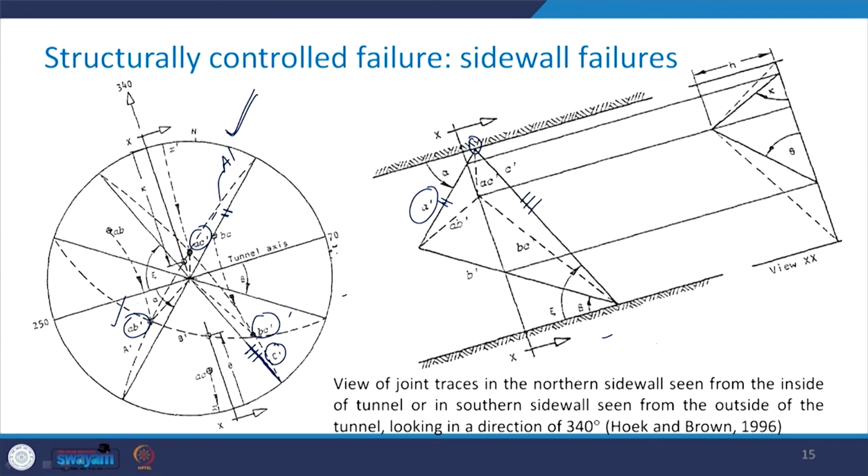Now, wherever this line intersects this end of the tunnel, from that point you draw a line which is parallel to this B prime. So, this is your B prime circle and this is its strike line. So, I draw a line parallel to this line in order to get this B prime. So, this is how I am going to get this complete triangle in this fashion.